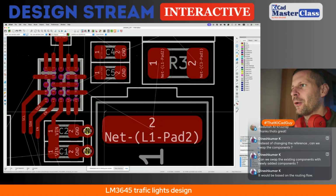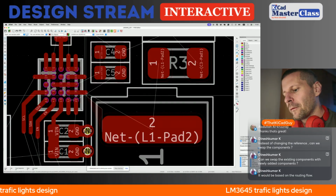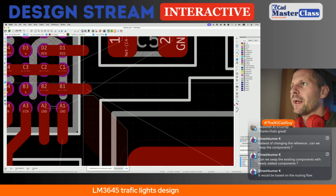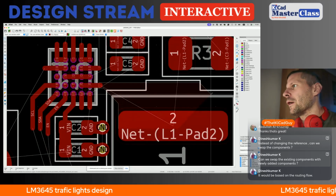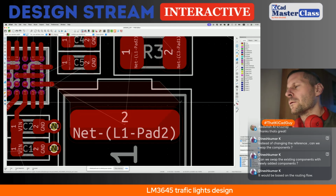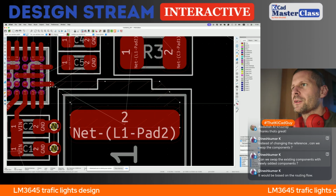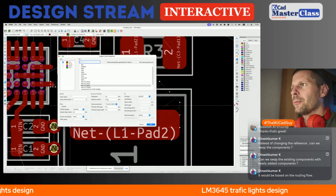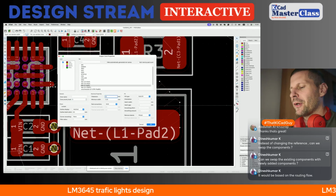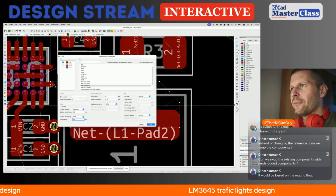So I will keep the default ones for this polygon, and then I will edit the shape. We want solid, some priority, clearance 0.2, fillet of 0.5. Let's start with it.